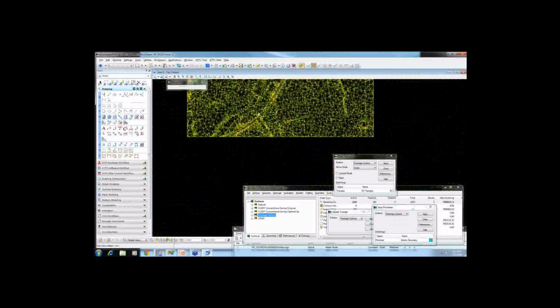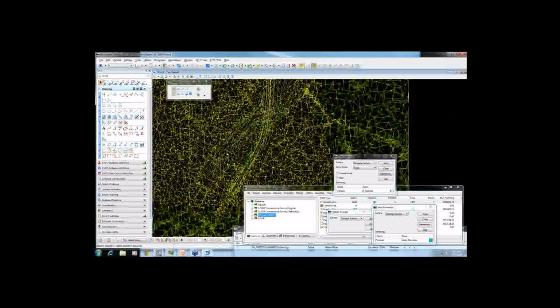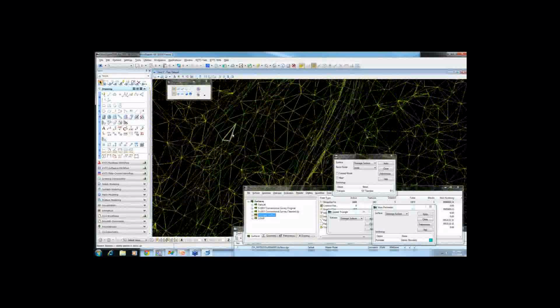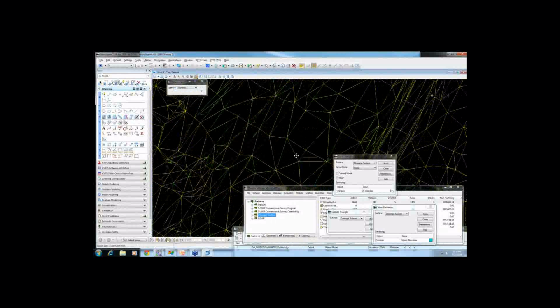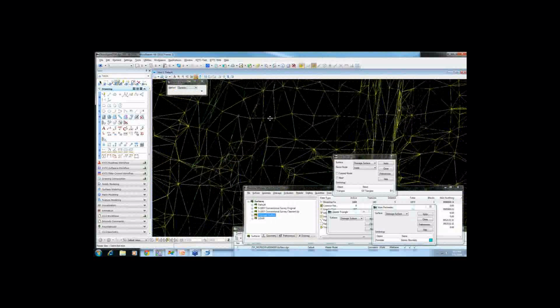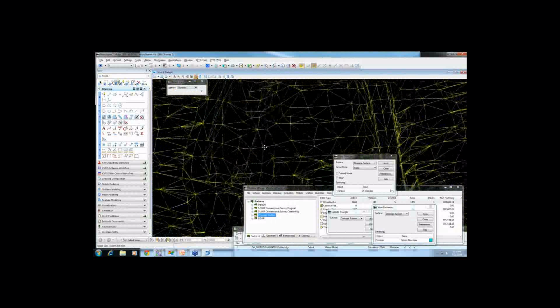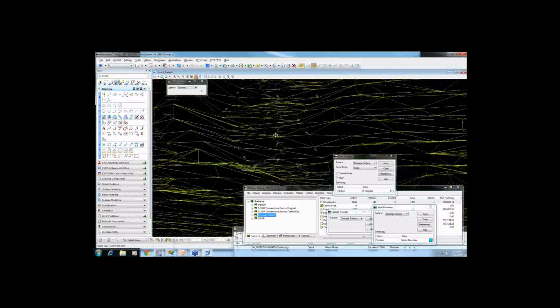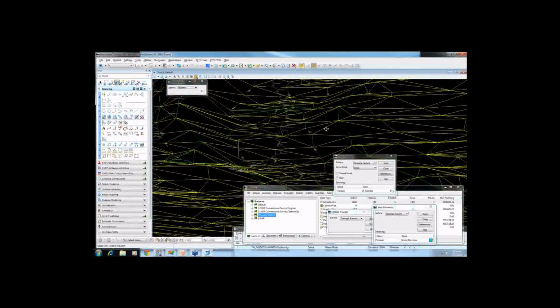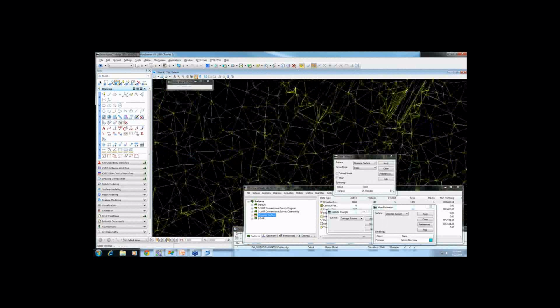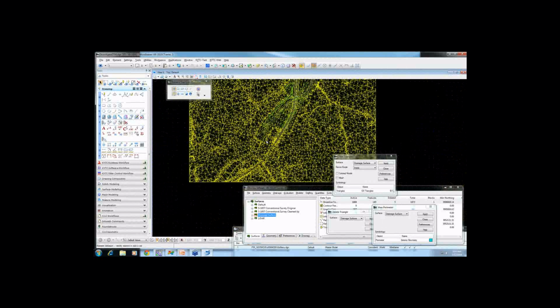It's not really accurate. And that reminds me of something else I meant to say a minute ago, is be sure to talk with your surveyors about what shots you need on the stream. Surveyors a lot of times haven't been trained in hydraulic modeling, don't know what it is you're doing with the data, possibly. So a lot of surveyors might pick up the bottom of the channel and the top of bank, and then you're going to get a triangular channel that doesn't really describe the geometry of the channel. So be sure you communicate with your surveyor and make sure you get the information that you need.